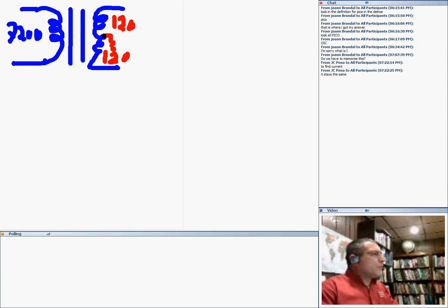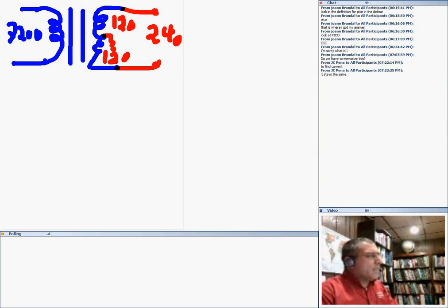And guess what? When you put the two coils together in series, what do you get? The voltage that you have in residential, 240. Two coils connected in series. You just get rid of the little one so it doesn't confuse you.